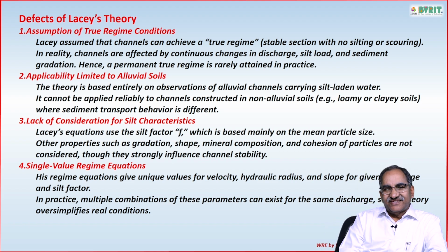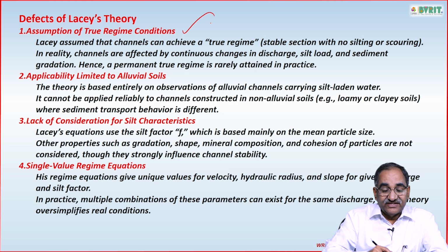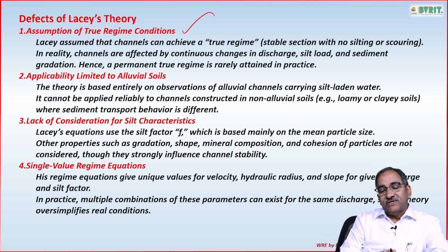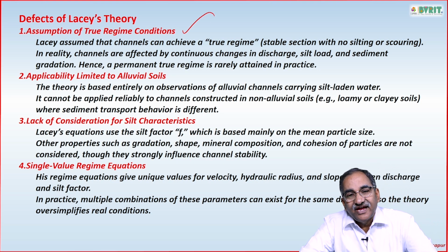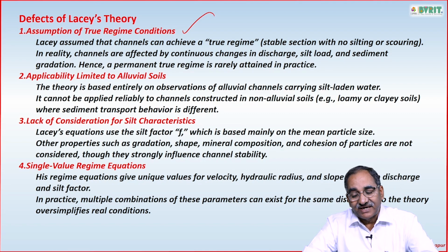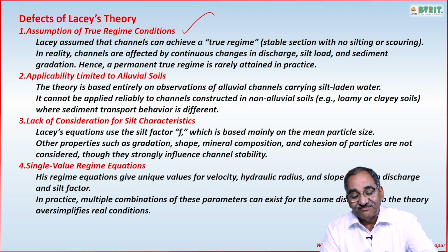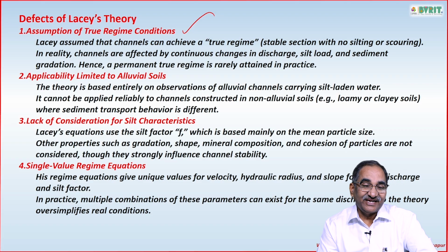So what are the defects in that? The first defect is the true regime conditions. Lacey assumed that the channel achieved a true regime actually, a stable section with no silting, no scouring. But generally the channels are affected by continuous changes in discharge, silt load and sediment gradation.